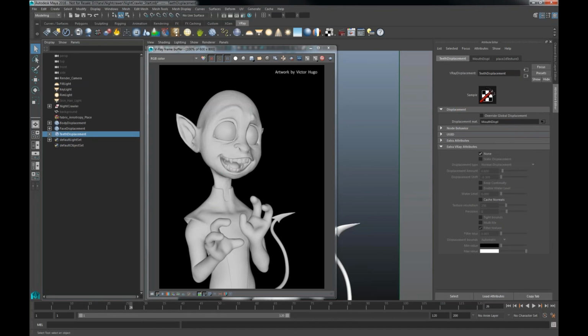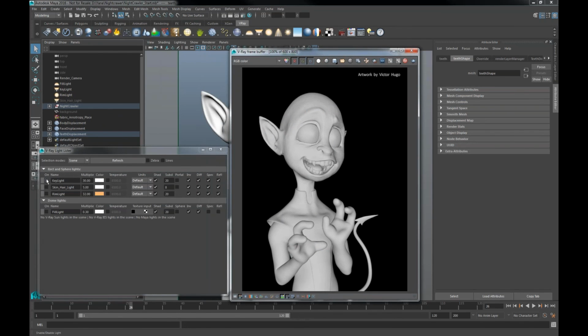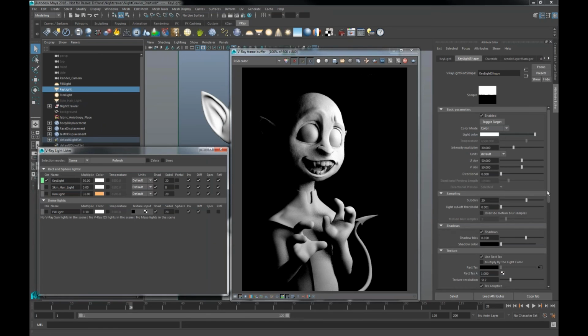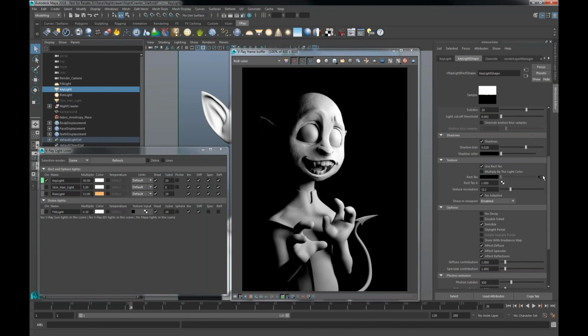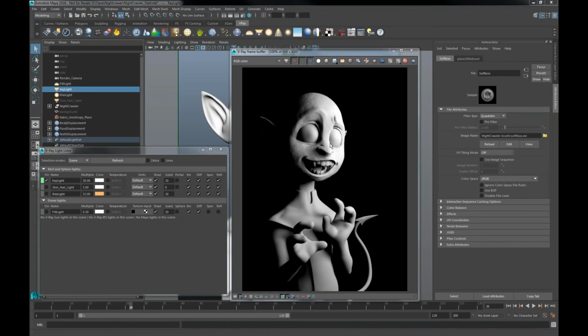Victor Hugo has used a common technique called three-point lighting, which is typical for a studio setup. And here I am going to use the RT in combination with the light lister, so you can see the result. I have here a key light, and this is the strongest light in my scene. It is a rectangular light, and here I have plugged in a texture. So this is the texture, so I can simulate a real studio softbox with it. Using this texture, I have a nice gradient from the light.